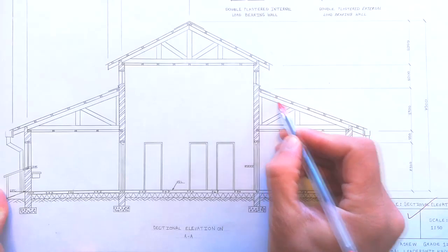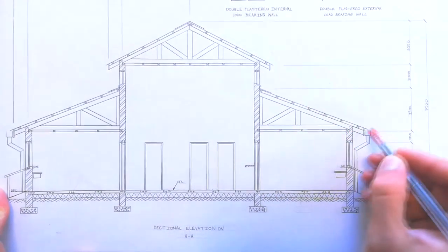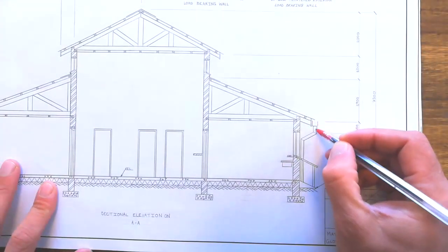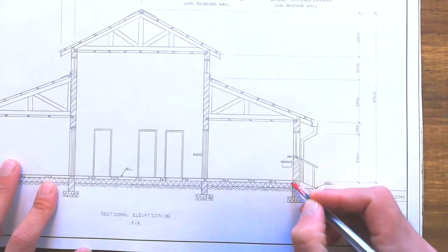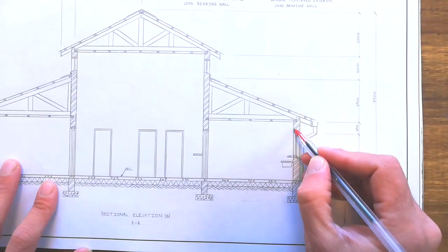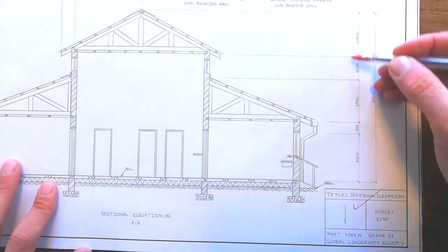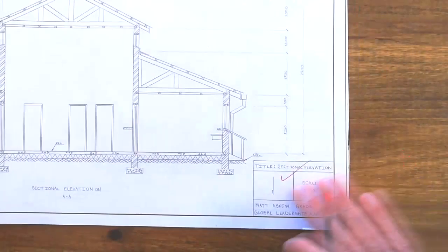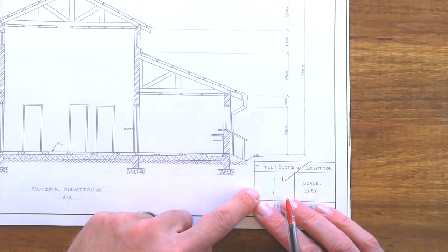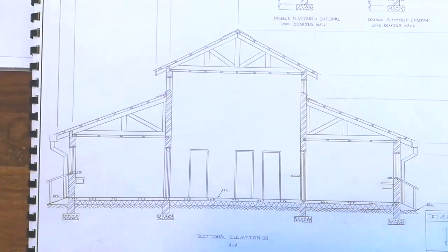Okay, that includes your purlins, your rafters, your ceiling, your wall plates, your overhang, fascia boards, your gutters, downpipes, access to the building. In this case, there was a little bit of a ramp here. You've got your external walls, and your key measurements on the sides. And you can see here they've done a little bit of a downgraded title block because it's only a requirement on the initial one. Right, let's look at another sectional elevation.